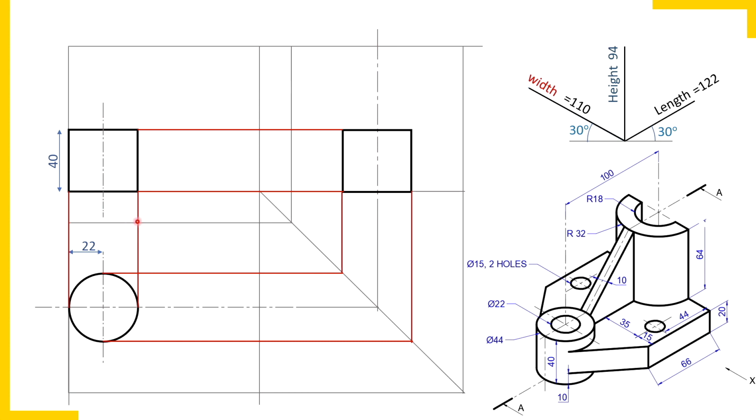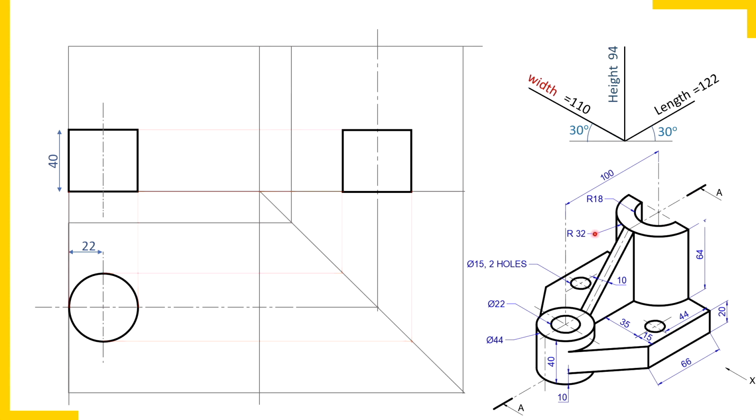Okay. So remember, once again, we'll draw that smaller detail, that is the hole, later. Let's proceed to the semi-cylinder. It has a semicircular slot. Right now don't worry about the slot. First the semi-cylinder, then we'll make the slot. So like this cylinder we are drawing, the semi-cylinder also; the slot will be drawn later. In the top view, a semicircle, and in the remaining two views a rectangle. It's that simple. So look at the center, it is extreme right on the axis of symmetry. So here it is the center.